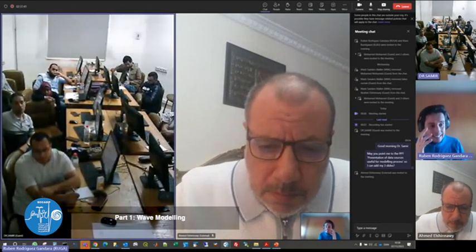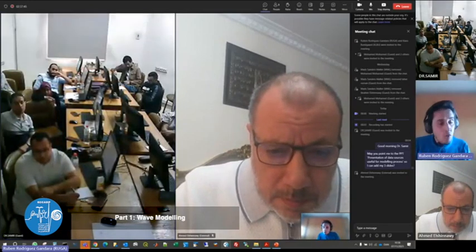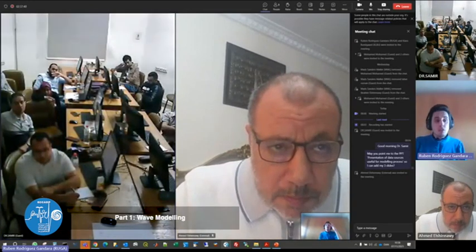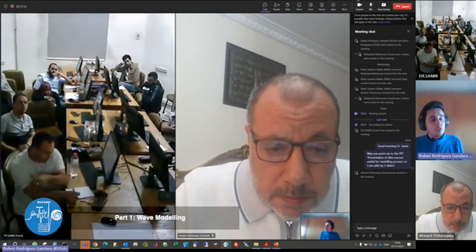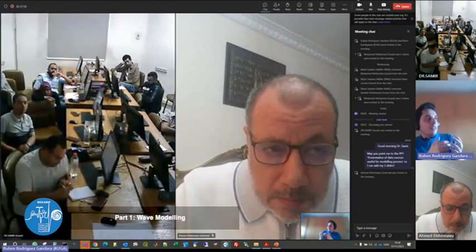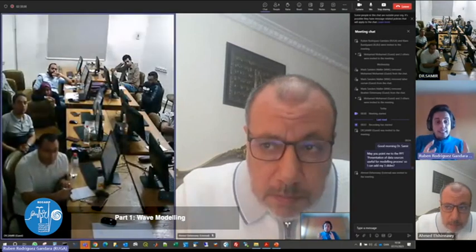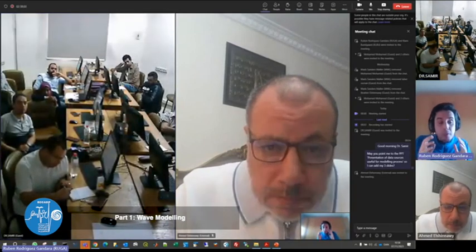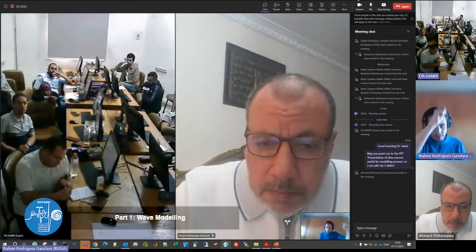Those are statistical parameters of a sea state of 1 hour or 3 hours, and then you have a description of, I don't know, 10% of the time waves of significant wave height of 10 meters, and 30% of the time wave heights of 2 meters. You know the statistics, but the program will not be able to tell you how to draw that single wave.